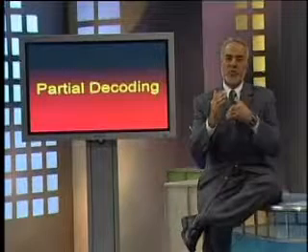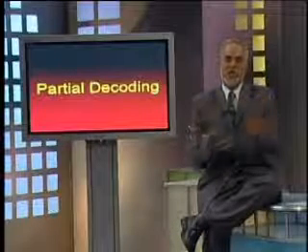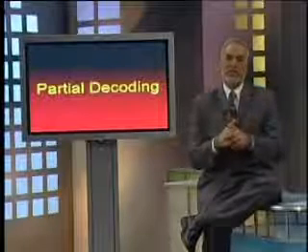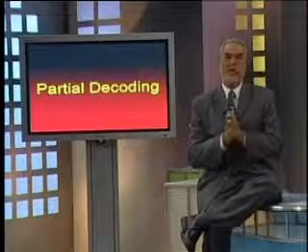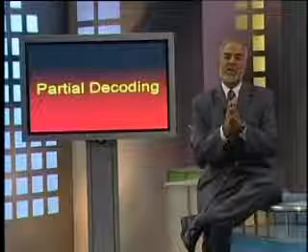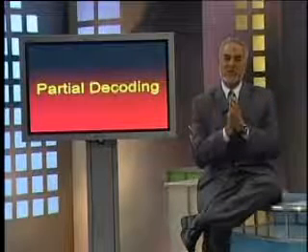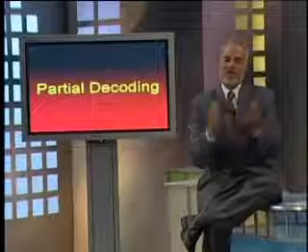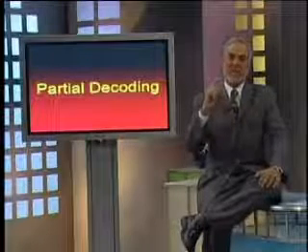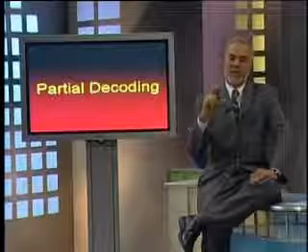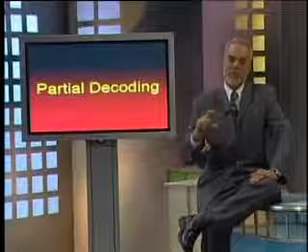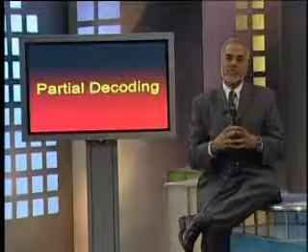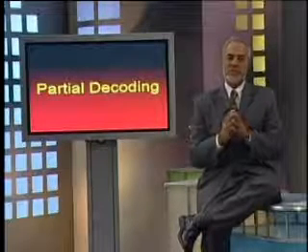From 0 to 255 would become the effective address space, or we could say that the total address space of which is 64K in Falcon A if we utilized 16 bits of address. However, if the upper 8 bits are just neglected, we don't use these, then the addressable space would become 0 to 255. The next would be again from 0 to 255, and we have all addresses effectively mapped to the same address from 0 to 255.